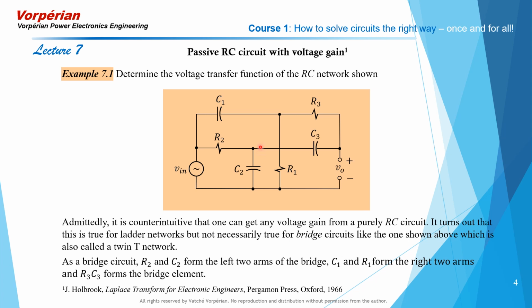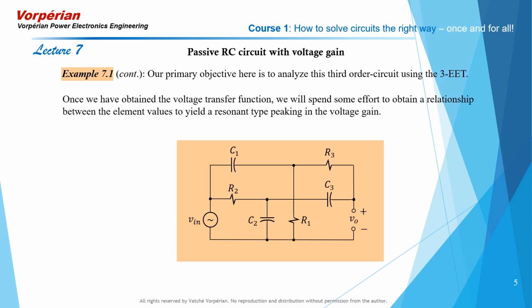Now I should say that Holbrook synthesized this circuit, and he did not simply stumble across it while analyzing a whole bunch of circuits. I am, however, using this circuit to demonstrate the 3 extra element theorem simply because it is an interesting one. Once we have obtained the transfer function, we will spend some time trying to determine the relationship between the element values that will result in a resonant type peaking in the voltage gain.